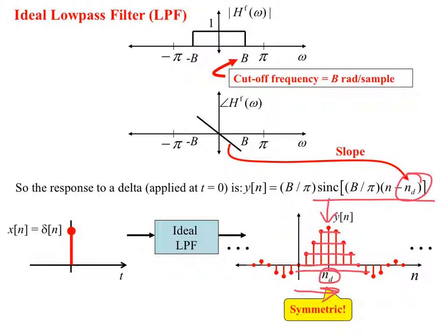Notice also that the further out we shift with a larger and larger n sub d, the more and more of this actually shows up to the right of n equal to 0, which becomes available to us, as we'll see, for making this into part of a causal version. So we see that this thing is not causal, and we go, uh-oh, we've got a non-causal impulse response.